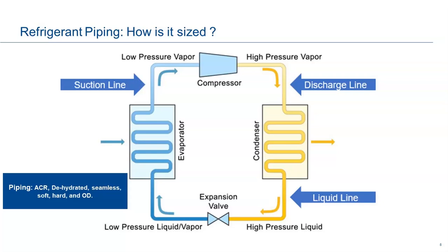And just to show you how important this refrigerant line is, for example, if we were to use an old line set going into a system and this liquid line was too small, you know what would happen there, okay? It would act almost like a metering device, and it would build up pressure and go back to the compressor and run hotter. That's going to take it out of the envelope. It's also going to raise the compression ratio. And compression ratio is the number one reason that compressors fail out there, okay? The number one reason, it's overheat, all right?